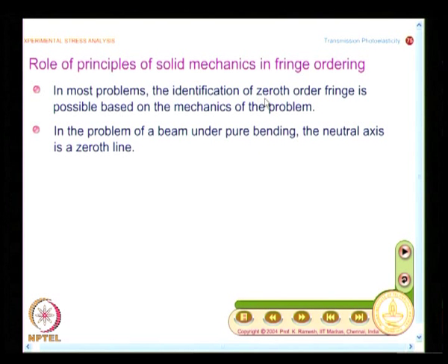See, if I have the zeroth fringe order and if I know the gradient information, it is possible for me to label the fringes. And I can get the gradient information by looking at a color code. And once I mention zeroth fringe order, let us also look at the exceptions, because that was also discussed briefly when we looked at properties of isochromatic and isoclinic fringe fields.